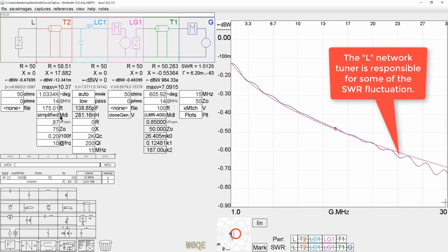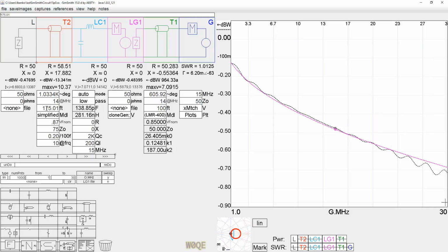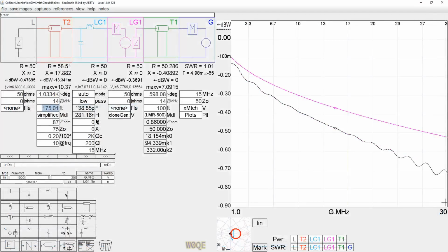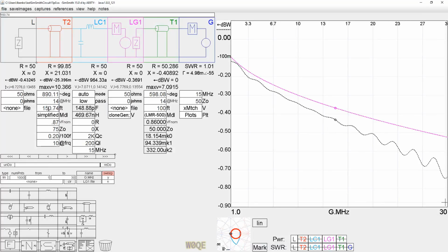So this is what we get. We can go 1.75 times as far with this free coax as we can with our purchased coax. And you could say, well, I'm going to spend a little more money than LMR 400. So let's go buy LMR 500. Now we've got to compare it again. Now I can only go 1.336 times as far.